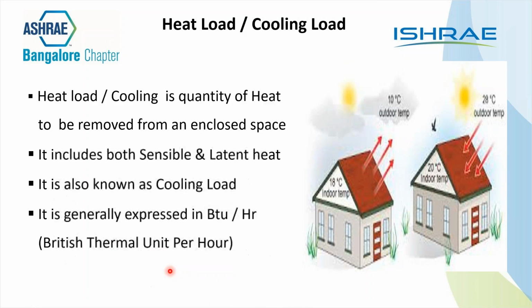Heating load or cooling load is nothing but the heat load, or the quantity of heat to be removed from an enclosed space. It includes both sensible heat and latent heat. It is also known as cooling load, and it is generally expressed in British thermal units per hour. So this is what we have been talking about now. Load is heating load or cooling load. That means the amount of heat to be removed. It has a combination of both sensible heat and latent heat.